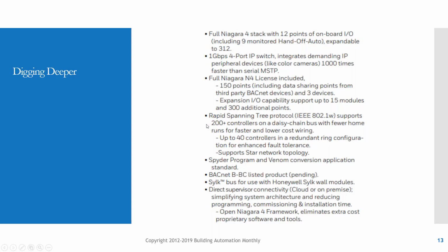I told you, it's hit or miss. I went and looked this up and I didn't get a clear answer as to the actual device capacity on a trunk segment. I will tell you that I would not feel comfortable with having 200 controllers on a trunk segment for the reasons I covered in the bus architecture of failure points, until manufacturers address that.